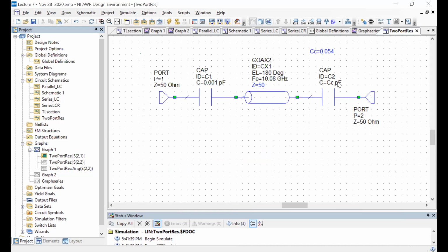And how much is roughly the same power you would have used if you were exciting it from port 2 and measuring a reflection coefficient. So the ratio of those two powers will be determined by the ratio of these two capacitors roughly, and then you can choose that. So it doesn't prevent you from doing your measurement. You just have to put more power here and just look at what's coming out of this side and not bother about the other side. Okay, let me pause here and ask if there are any questions about this part.